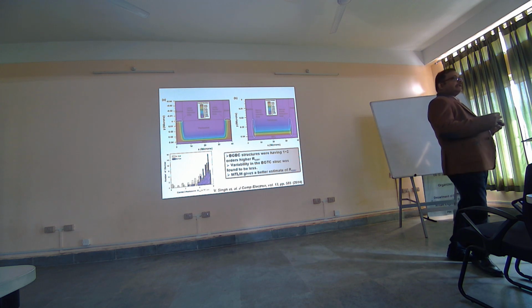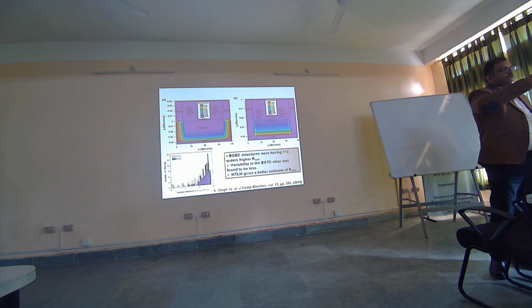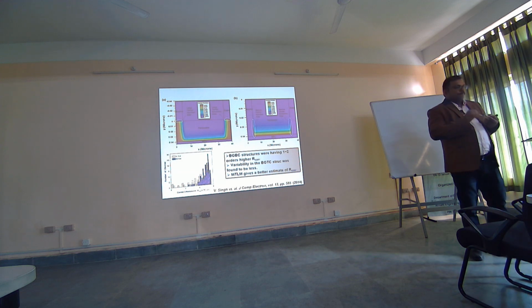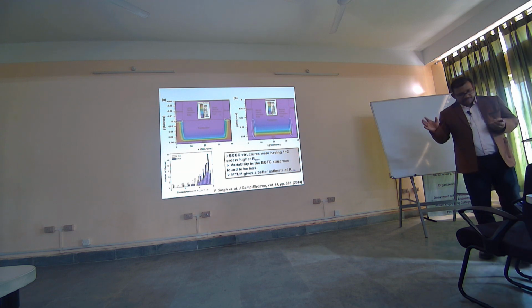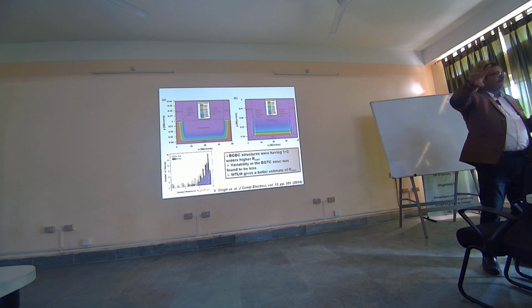Band gap has a relation to what we call the intrinsic charge carrier concentration. If I have a higher band gap material, my intrinsic charge carrier concentration will be less. But it has nothing to do with mobility as such. Number two, most organic semiconductors have band gaps typically in the visible part of the spectrum and IR.